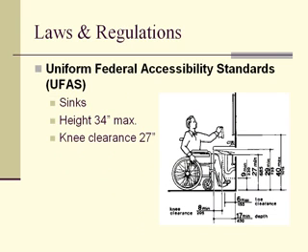At the same time, the faucets, which many times, if we look at a lot of the older ones, are probably not something that is operable with one fist. These faucets should be operable, and all the operable parts should be operable with one hand. Basically, a closed fist should not require tight pinching, grasping, or turning of the wrist to operate. That's the general concept behind that, to facilitate somebody utilizing these elements.